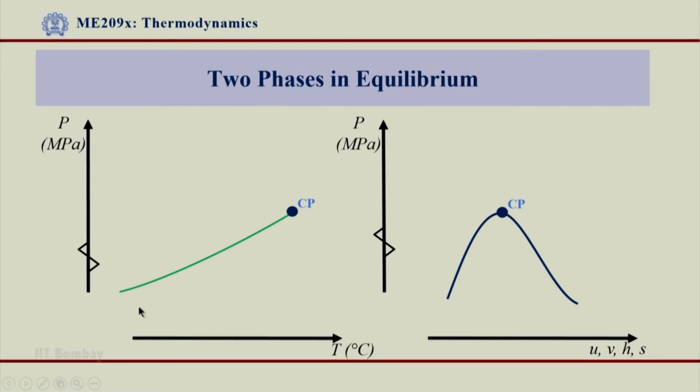So, again let us have an LV saturation line here, and we had seen that we heated a subcooled liquid from 20 degree centigrade and went up to 300 degree centigrade. I am showing just those points from 20 degree centigrade to 300 degree centigrade, and this process change has happened at 1 atmospheric pressure, and therefore the boiling point here in this case is 100 degree centigrade.